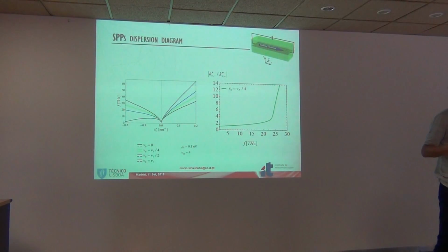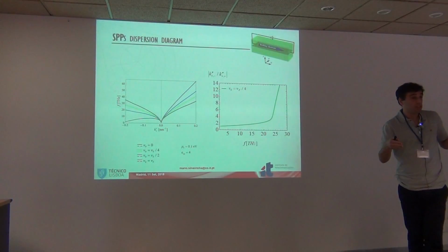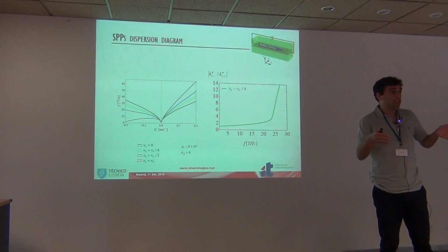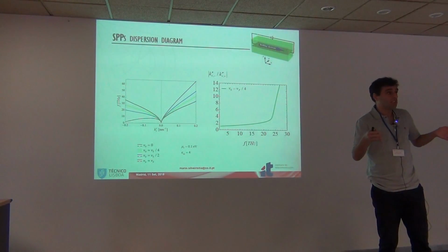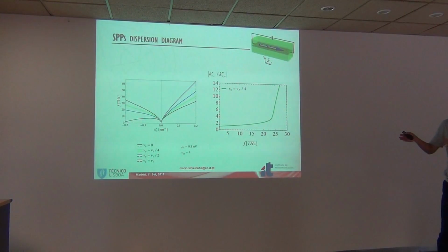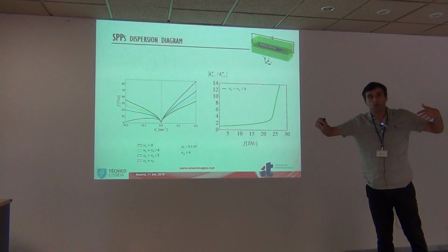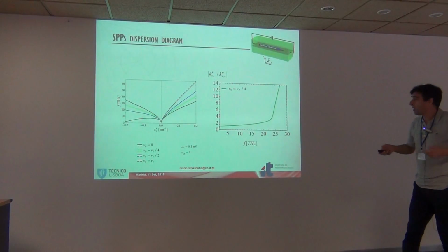So effectively, we have some type of optical isolator, but at the nanoscale, and with a length of maybe 100 nanometers, you can have a very good optical isolator with graphene. You don't need these bulky systems, which at this frequency would have lengths of the order of maybe 10 microns, so maybe 1,000 times bigger.